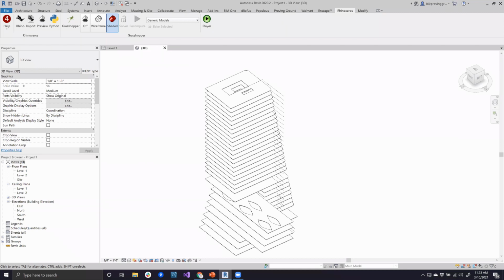Let's see here. First: is the data generated by Conveyor actions, like indicating something as a floor, stored in the 3DM, or is it lost when Conveyor is closed? So it is stored in the 3DM in the form of classifications. When I classify a surface as a floor, that object is classified as a floor, and if I close the Rhino file and then import that in, then yes, it will maintain that persistence.